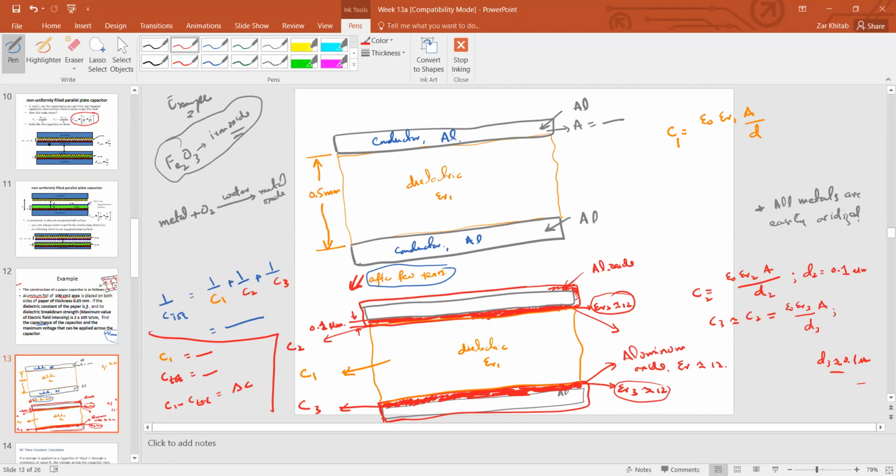So this kind of information you need to put on the specification sheet or on the manual of the capacitor. So see, a del C capacitance change has occurred in C1. So how much percent change will occur? This will give you the percent change in capacitance, after say 3 years, 4 years. So you need to build such graphs, basically simulate them to show the client.